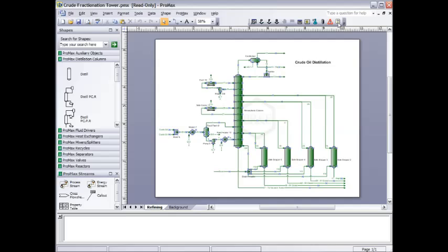In addition to the Flowsheet menu option, you can also create a new flowsheet by right-clicking down on the current Flowsheet tab. One of the options that appears after right-clicking is to add flowsheet. Selecting Insert Page instead will add a new Visio page, not a ProMax flowsheet.